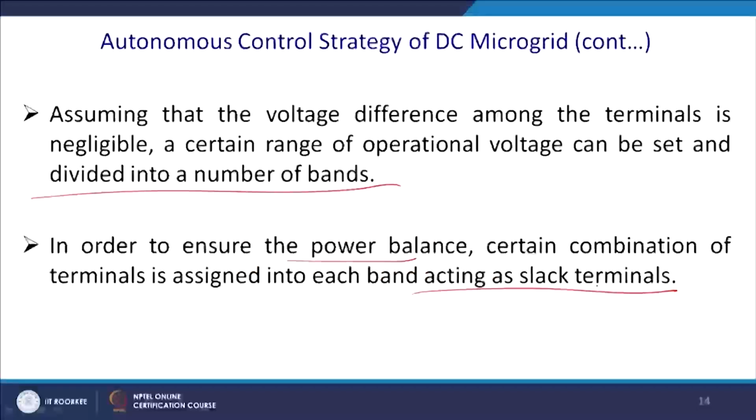So, that is what happens. Let us say solar is healthy and grid price is low, then you make solar and the grid your slack points, and others are required to follow. So, the battery may charge or discharge depending on the requirement. But after some time, when the grid price increases in the evening, and maybe you have plenty of wind, then wind and the battery will take over, and that will be the slack bus, and others are required to synchronize.